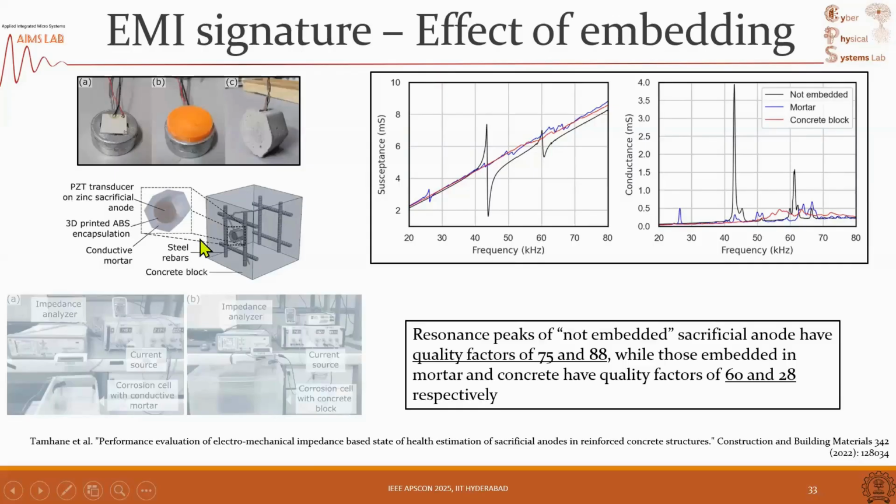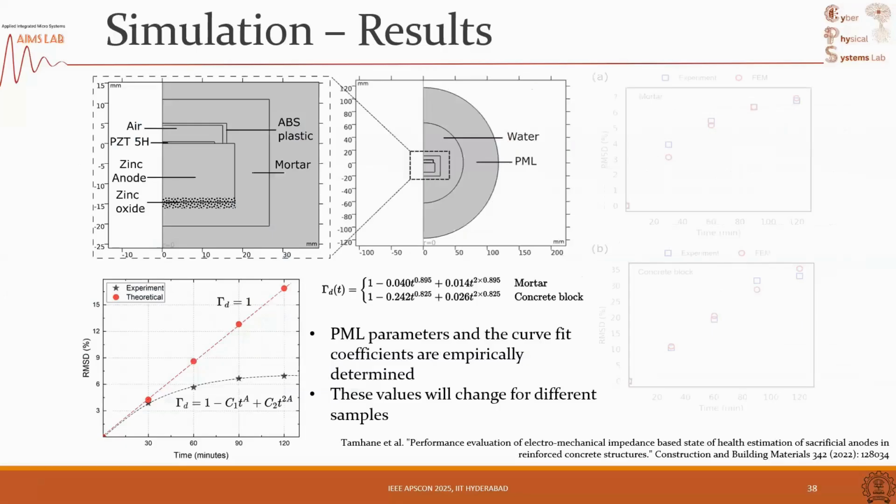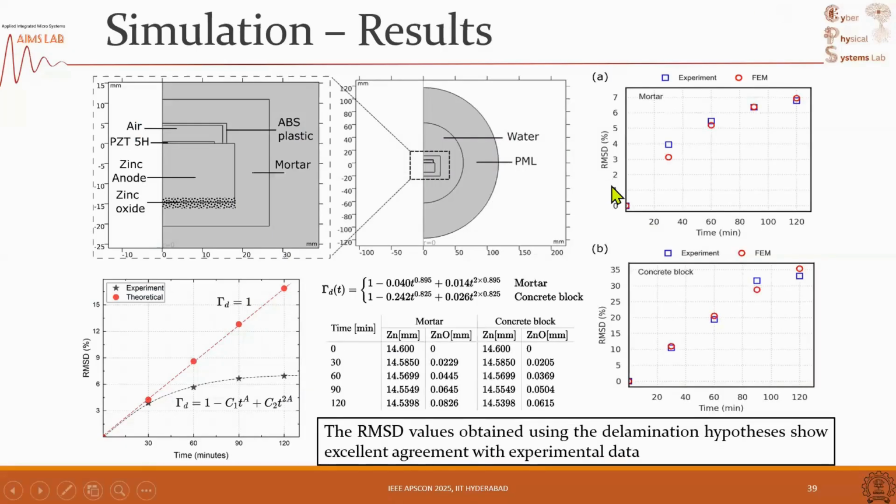What is good about this is this also works when this resonator is surrounded by solid concrete. Because with MEMS typically, if you have liquid or something surrounding it, the quality factors really drop and the sensing is affected. Here, because my structure is very large, the sensing mechanism can still be used. It is still non-linear, but we did a lot of simulations and again, we can model and understand the non-linearity. So what we learned was we can use this method, so we'll see where that goes.